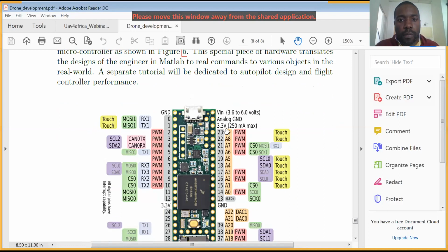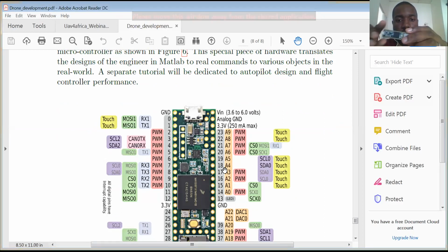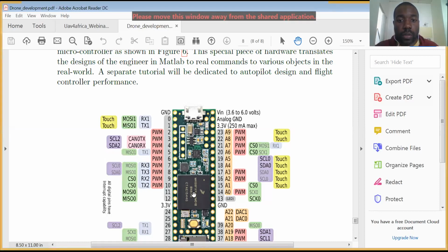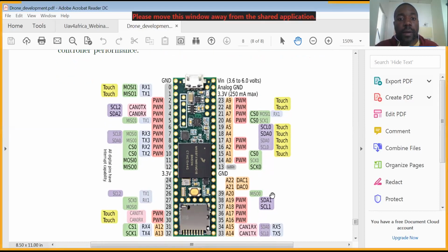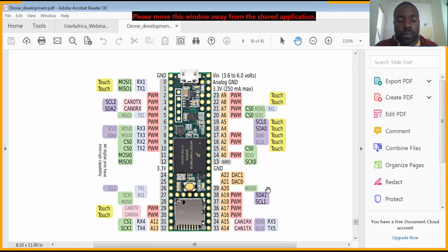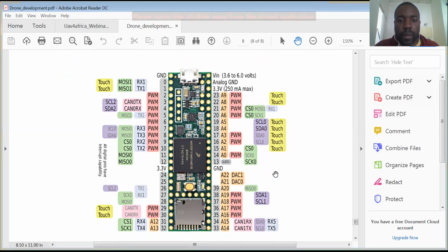It's got the power of quite a few pins, and the whole idea with the pins is that it's got wiring that you can connect all sorts of motors, GPS for location, IMUs for measuring rate, like we spoke about. Then velocity comes from a measurement too, and that is, again, a sensor that measures that. It's called an airspeed sensor.